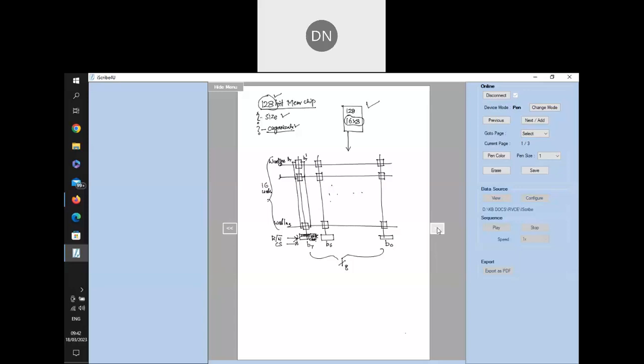Now the data bits which are connected to the processor data bus will be bidirectional. I can write into this, and I can read from this. That is why we draw it like this, one for reading and one for writing. So now I have understood that to design any memory chip, we require a sense and write circuit for every column bit. All the columns of the words are shorted together and provide one bit of data. So now we have understood how columns are connected together.